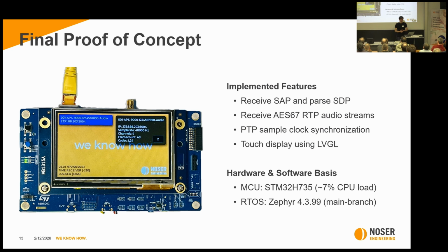Final proof of concept: it works. I can now receive the Session Announcement Protocol, this little text file. I can parse the text file. I can receive the AES67 RTP audio stream over multicast. I can synchronize the local audio clock to the PTP clock. And of course, touch and LVGL are working just flawlessly. This was really a joy to implement.